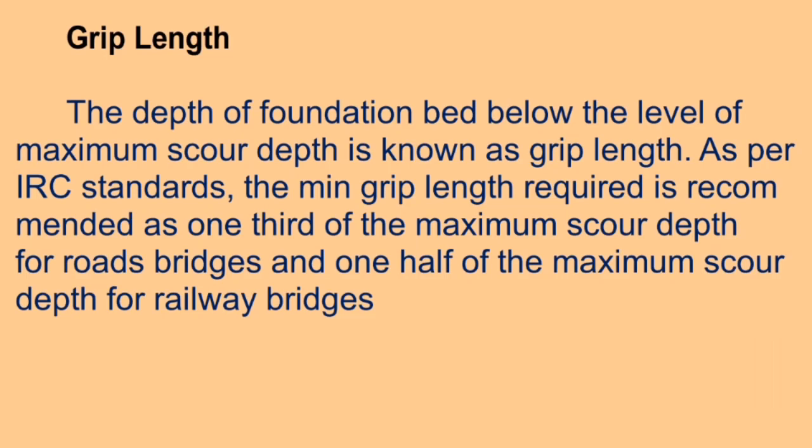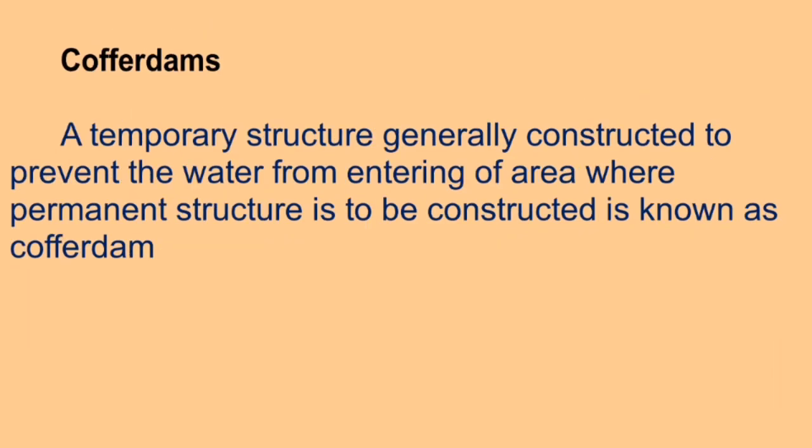As per IRC standards, the minimum grip length required is recommended as 1/3 of the maximum scour depth for road bridges and 1/2 of the maximum scour depth for railway bridges. Coffer dams. Coffer dams are temporary structures generally constructed to prevent the water from entering an area where a permanent structure is to be constructed.